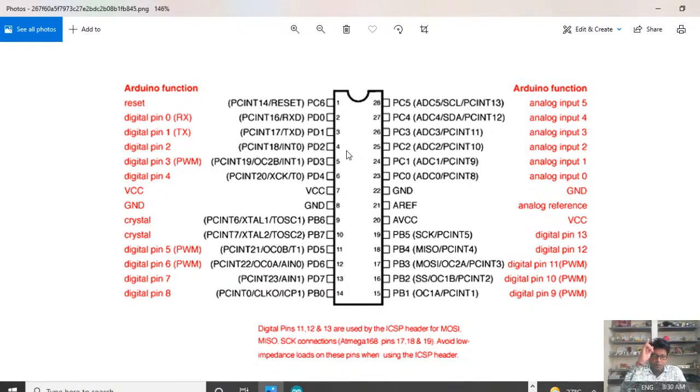But if I use each channel for a distinct pulse, and let the complementary pulse be generated with some delay and dead time, then I can control 6 legs. So it is always better to generate the complementary pulse externally.